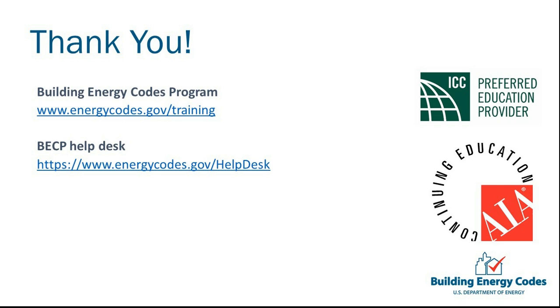Yeah, sure. This approach is kind of along the line of what I was trying to explain, in that you would have a baseline building, and there's a tool that PNNL has developed that will help use this approach, where you'd model a baseline building, and the baseline building would have a reference system in it. Let's take, for example, a small office, so it's got a rooftop unit on it. And then you would model your proposed building mechanical system and compare it against the baseline building. So it's very much like Appendix G, but on just the mechanical system. So, for example, if the code requires an economizer on a rooftop unit, and for some reason you don't want an economizer, you could go in and model it and prove that you're better than that system, and then you would be approved to use it.